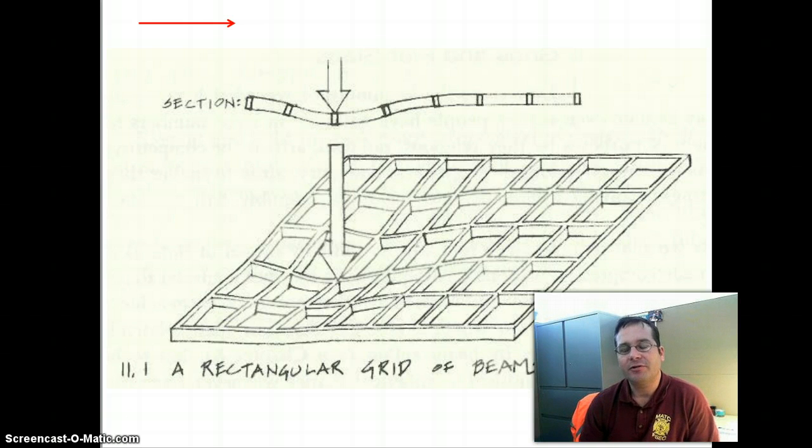And the only way to make materials that are anisotropic span long distances is to develop a curved shape. So if you think about long spans of antiquity, they were always arches or domes. Even wood trusses generally fall under this limitation, even though we know that wood is not nearly as anisotropic as stone. If you wanted a long span like a grocery store or a bowling alley, a common truss was the bowstring truss. What started to change that was the development of building materials that were more isotropic.